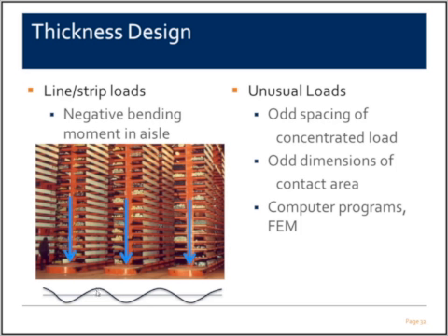And in these areas, you'll have negative moments and flexural stresses; these areas represent the aisles. Flexural stresses may develop, and so you should not assume that you should put joints in the aisles immediately. So flexural stress-related cracking in the aisles might be an issue.